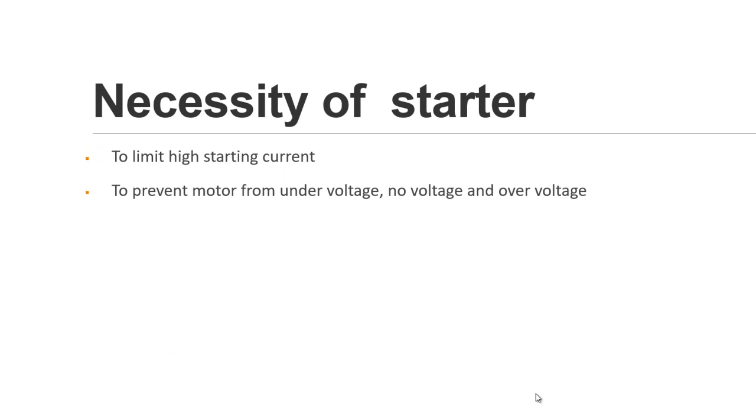What is the necessity of the starter actually? The starter we will use to limit the high starting current and to prevent the motor from under voltage, no voltage and over voltage. Because of that, the starter is necessary.